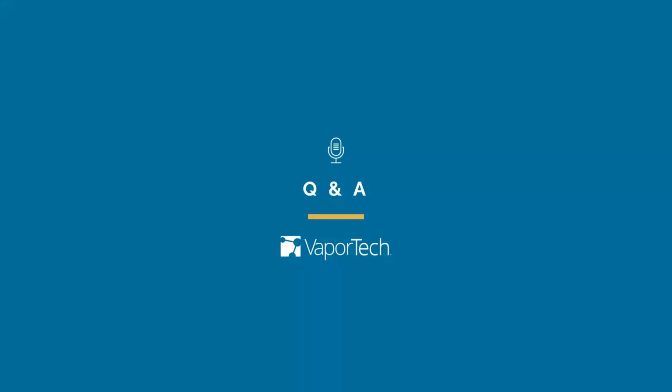If you compare titanium nitride to a zirconium nitride, they have similar color. Not that that's important for the performance of the component or the tool. Titanium nitride historically has been more used in machining applications, while zirconium nitride goes more towards applications where you need more resistance to the environment, and I'm talking about corrosion and oxidation.